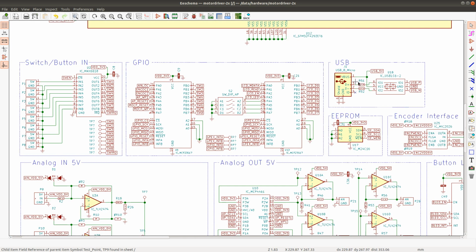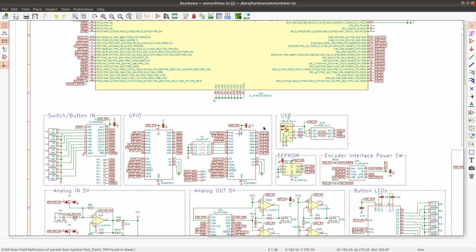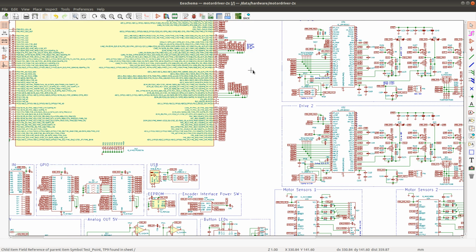So, what else here? Let's see. So hopefully the test points of 1 × 1 millimeters are going to be fine for most of these components and can just be placed along the track. It can be a little bit problematic to place test points for high-speed signals, because if you have a differential line and you have to place test points, then you either have stubs or you have to separate the differential line. But on this schematic we don't have any signals that are of such high speed that would be an issue, I think. Let's see.